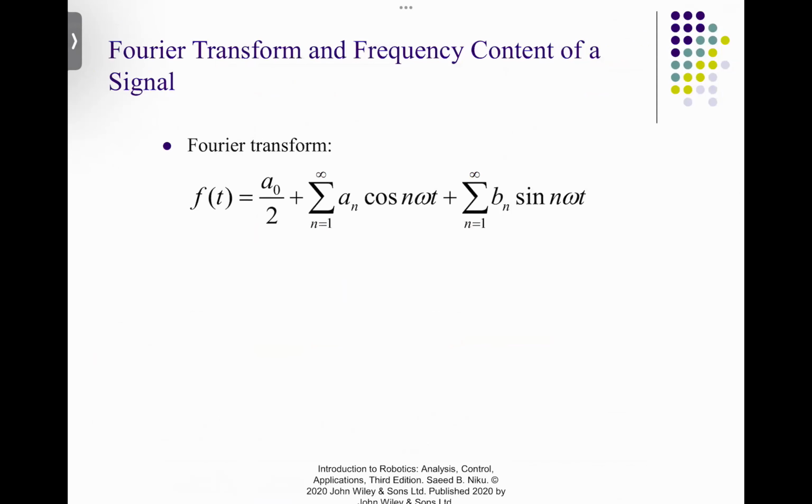One important thing when we analyze an image is that we can analyze it in terms of spatial coordinates, pixelations, or we can talk about it as frequency. If you have a signal that is periodic, you can decompose that periodic signal into a series of sines and cosines.